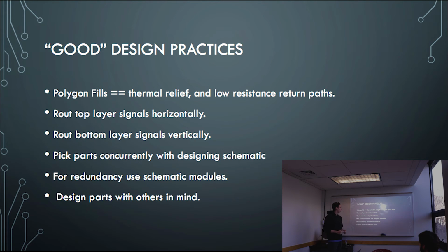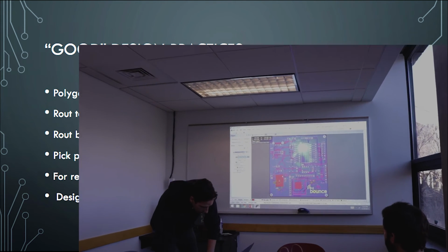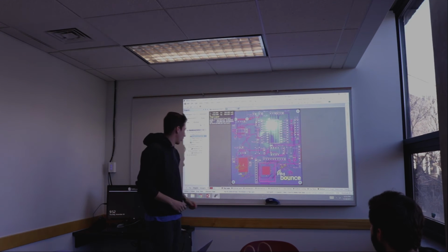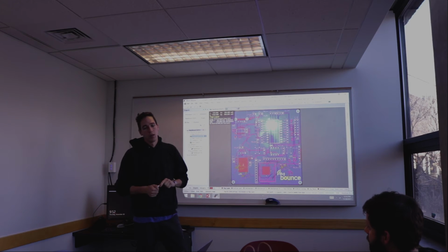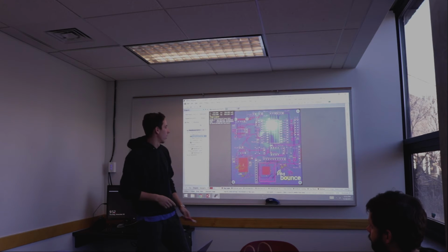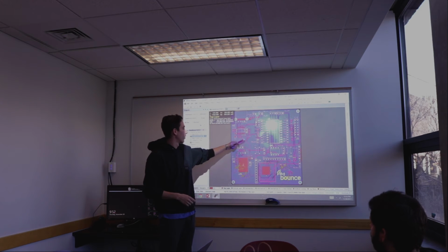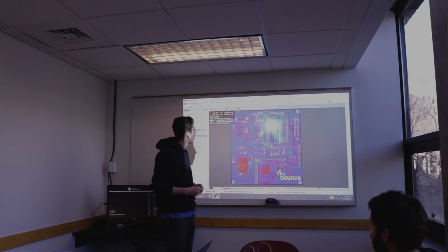So when I'm designing a board, I usually don't worry. I usually do a little thing where, when I know I need to connect a signal to ground, I change a via to the minimum hole size that Advanced Circuits will allow us, and then I just do this. I don't know if you guys can see it.